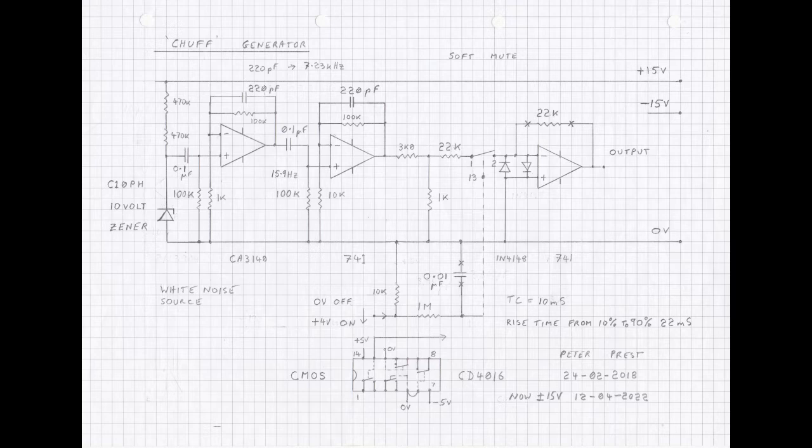The CD4016 is a 4-channel CMOS analog or digital switch, normally commanded abruptly on and off by means of an input logic signal. However, I discovered that if this logic signal is applied gradually via a resistor-capacitor network, progressive soft switching occurs. The CD4016 is supplied from plus and minus 5 volts. The analog signal must never exceed these values, so the previous op-amp is followed by an attenuator to avoid this. In the off state, the CD4016 has virtually infinite resistance, and in the fully on state, a resistance of just under 300 ohms.